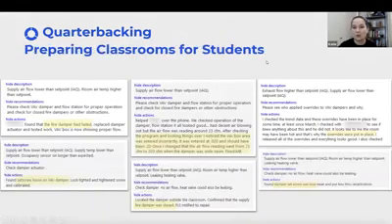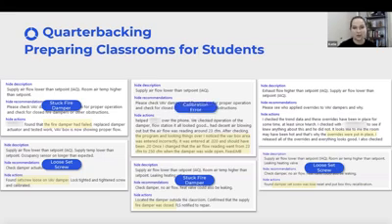And here are some real world examples of when a campus was preparing for the fall, some of the things they found using FDD that were related to IAQ at the zone level. I don't think any of these findings will be surprising to you: stuck fire dampers, loose set screws, calibration problems, programming overrides. These are all things we see every day when we respond to hot or cold calls.